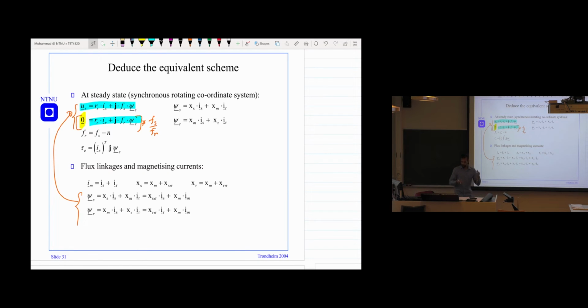That is the difference between the grid frequency and the rotor frequency. But here now we are providing it through a converter, and we have the capability to regulate the frequency, voltage, whatever we want, to have the desired frequency, desired torque, desired speed. So that is the advantage. So now we have the steady state equation.